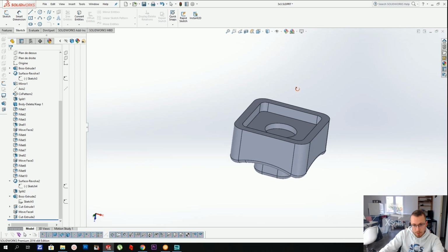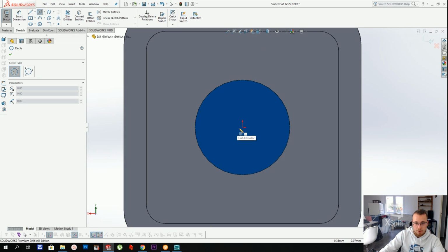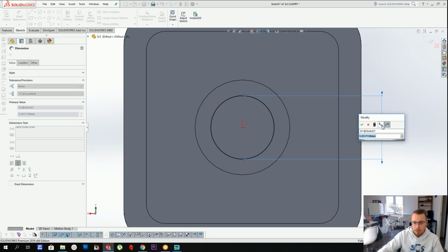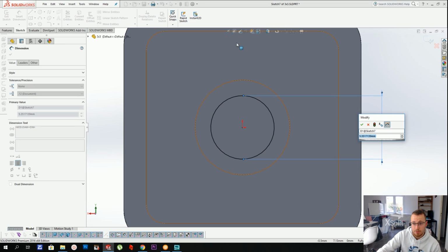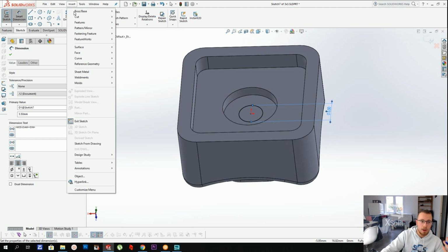Now that this is done, I'm going to create a hole for the screw, but I want it to be loose because the center, well, you're not screwing the center, you're screwing the center into the core. You're not putting a screw inside the center, so we're not going to need to put any tightness around the screw shaft. So M3 means that the shaft is 3 millimeters wide. So you're going to make the diameter 3.5 millimeters. That way it can just move freely around the screw.